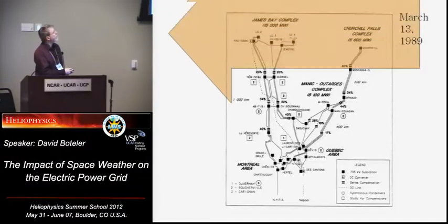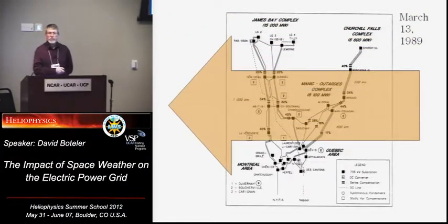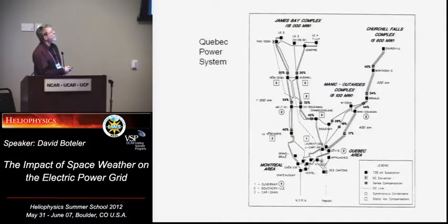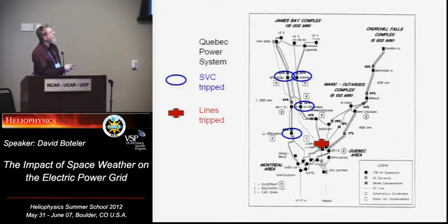On this day, an Aurora electrojet that's normally sat higher up across Hudson Bay moved down right across the top of the system, and that induced electric currents that flowed across the network. They caused problems with the transformers, and I'll explain this in more detail in a minute, and caused various devices that were maintaining stability of the network to trip out. So a sequence of things tripped out there. That then caused the lines to trip out because the system was starting to go unstable.